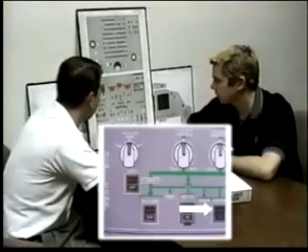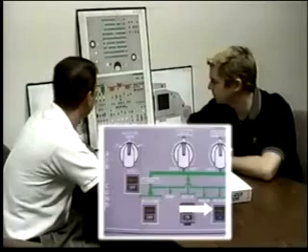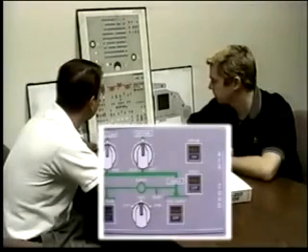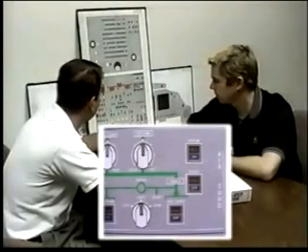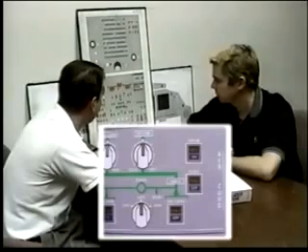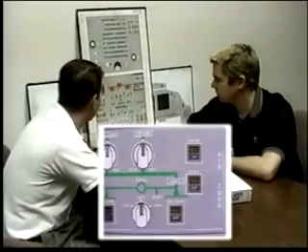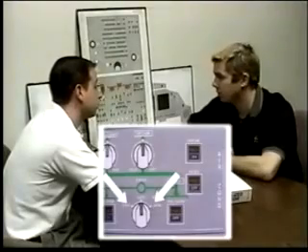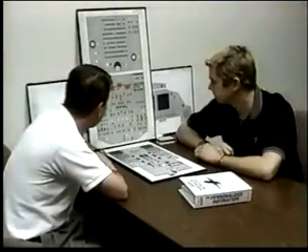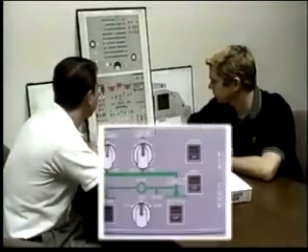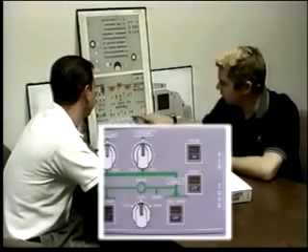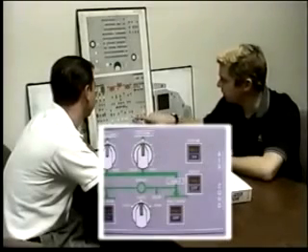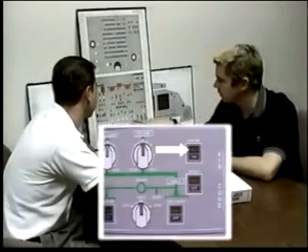What about fault on APU bleed? APU bleed leak only. The cross bleed selector, you told me with the selector in auto, it takes the same position of the APU bleed valve. However, what if I command shut or open? Shut or open is going to give you a shut valve or an open valve. Hot air valve. Both of these indicate an overheat or a valve disagreement. In this case, it's a duct overheat. In this case, it's a pack overheat.